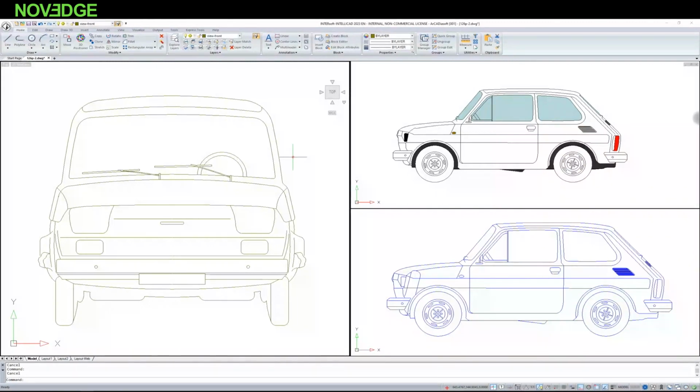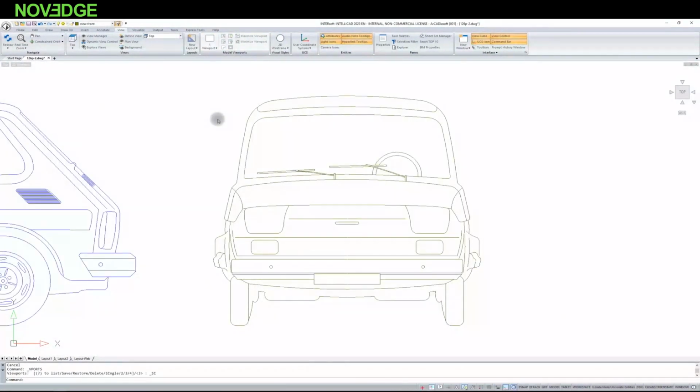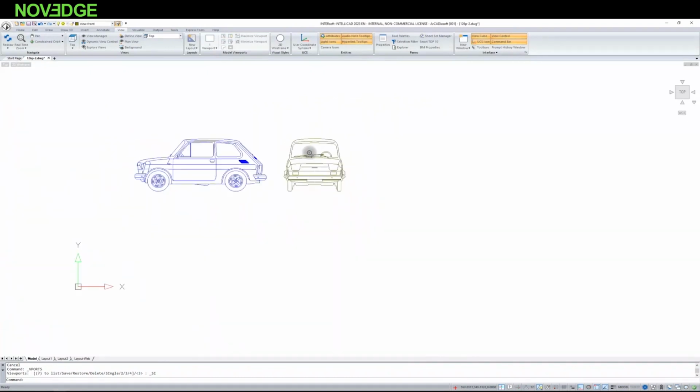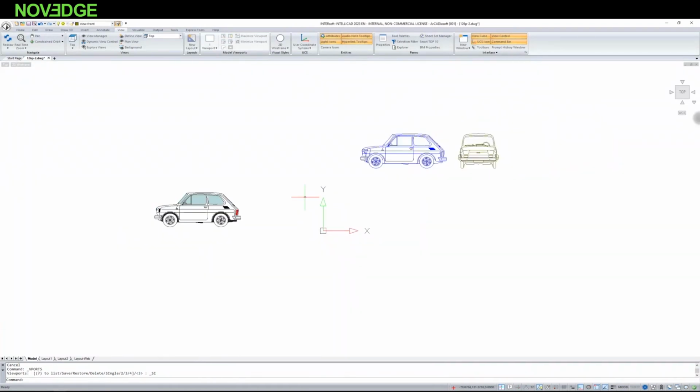You have a lot of elements in the project, but you don't always need all of them, and of course, you're only working on one piece at a time. If you want to make things easier, you can define a viewport on the view ribbon. They can be, as here, several on one model. There can also be just one. There's usually one viewport in the project, and please note as I zoom in, you can see all elements. You just see the 3-part viewports.